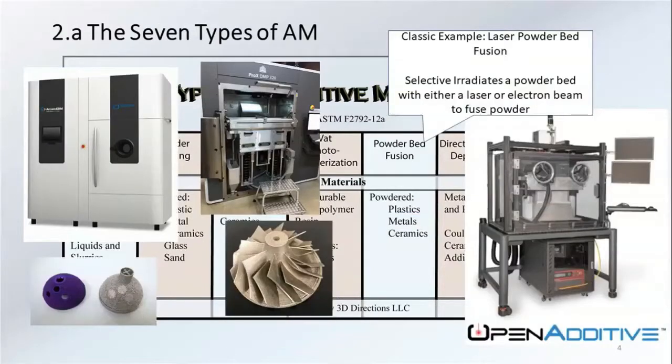There will be crossovers. So in powder bed fusion for metal, there is laser and then there is electron beam. Electron beam melting is typically done in a vacuum. The electron beam will also partially fuse all of the powder. And because of that, you do not need the same support structures that you need in laser powder bed fusion, where we don't typically heat the chamber, and you are using the laser to fully heat the metal up to melt temperature and back down, so you're welding.